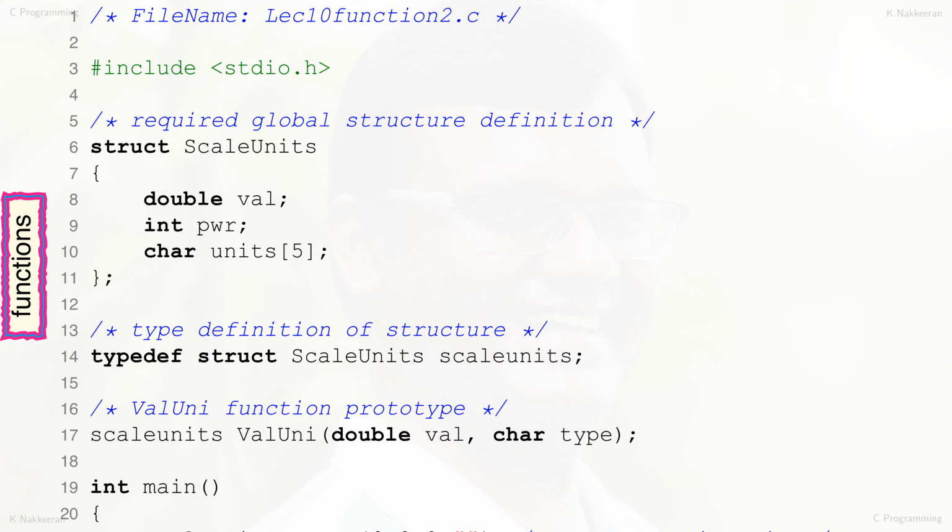If we write the device value conversion part as a function, it will become quite handy to call it whenever required. Let us amend the C program to separate the device value conversion part as a function that can be called with necessary parameters for the conversion to be performed. And after the conversion process, the converted value, number of decimal point positions moved to the left or right, and the appropriate higher or lower units are returned to the place where the function is invoked.